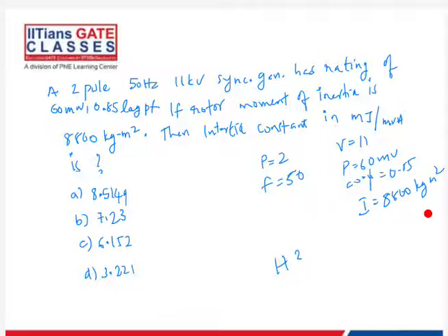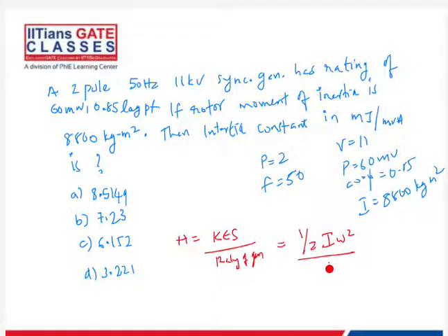Right. So they are asking you to calculate H, right? So what is its formula? This is a simple formula for substitution. It is the kinetic energy stored divided by the rating of the generator, right? What is kinetic energy stored? It is half I omega squared divided by S, right?